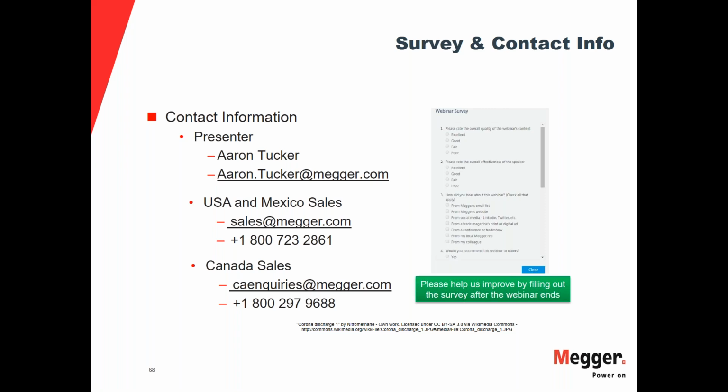Okay, when you go back to the OLTC test, where we distinguish between the DETC and the OLTC, if I'm looking at this question correctly, they're just asking every time they do the turns ratio on the OLTC, should they always do all 33 taps? And the answer is you should always do all 33 taps, because you don't know what the extreme ends could be. If they're different, you don't know if there is a fault between one of the phases or one of the taps, or whether you have an issue with the tap changer making it all the way from one end to the other.